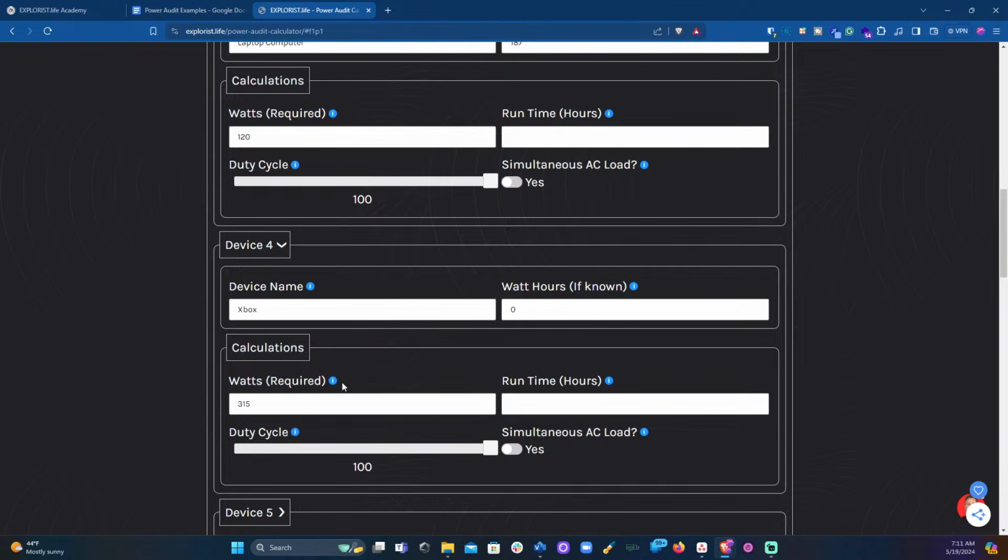So we plugged in our AC meter, and during 2 hours of gameplay, we had 629 watt hours. 629 watt hours, and so I'm going to put that in. That was for 2 hours of gameplay. So if you're using your AC meter and you play longer, this is a game of close enough, basically. If you play for 2.5 hours every night, or 5 hours every night, you just have to make sure that you factor those averages into your power audit, depending on how important these loads are to you. So I've got 629 watt hours.